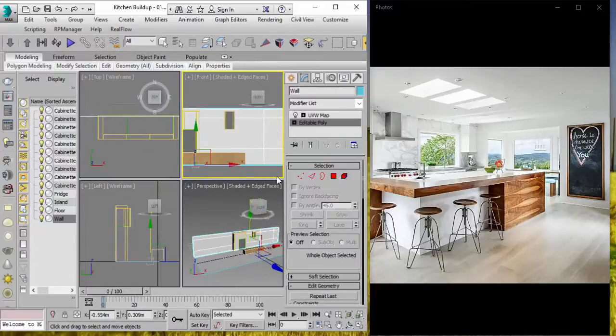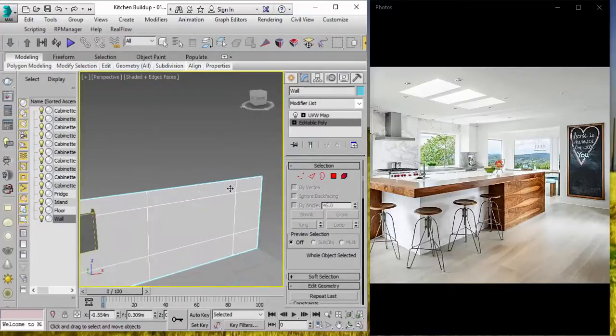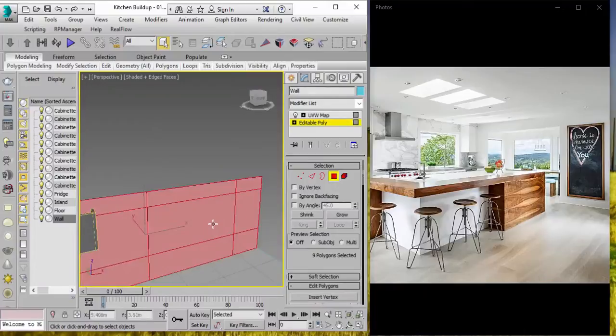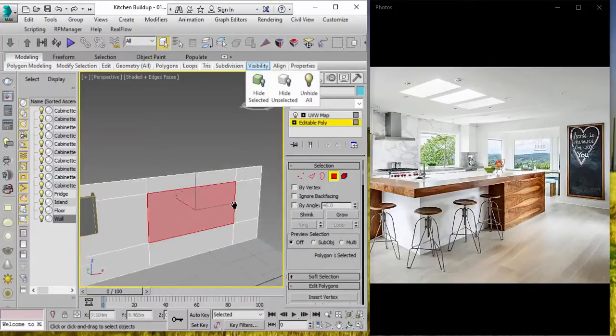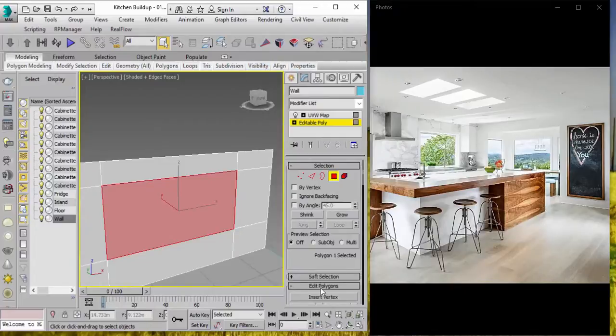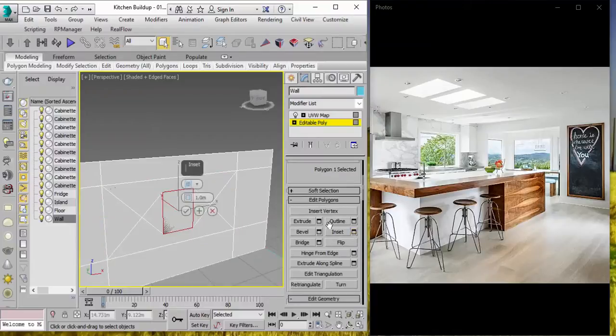Okay. Great stuff. And then we need to cut through the opening, of course, of the window. And so please select that. And then we're going to select insert settings. There we go. And then we're going to reduce the values. There we go. Be gentle with it because we're just trying to create that structure to add just a bit of detail. All right. Click OK.